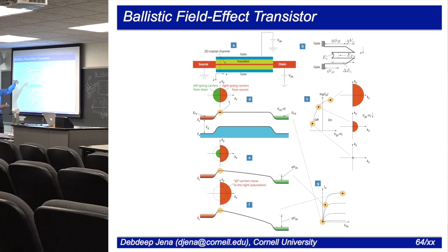But weirdly, you might think that the red will remain the same because this really has not changed, right? But the most important thing about the transistor really is that no, it has to change, because the electron density at the source injection point is not controlled by the source or the drain.